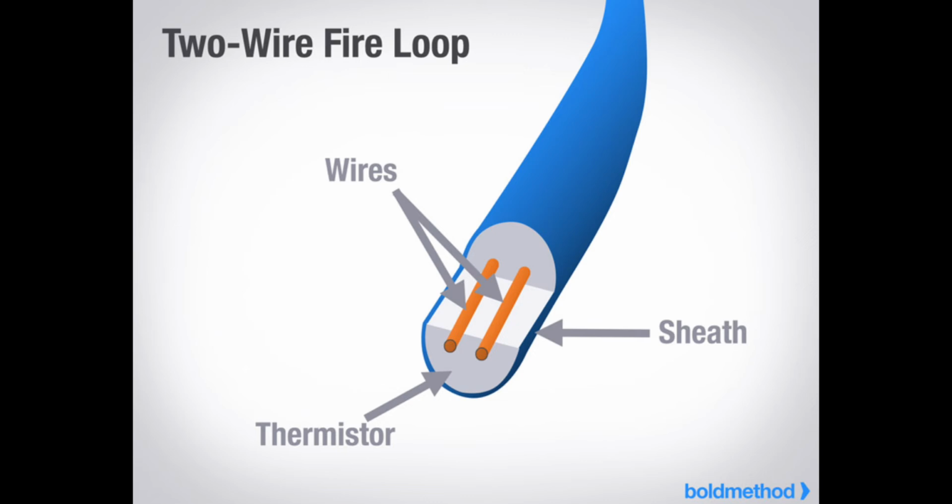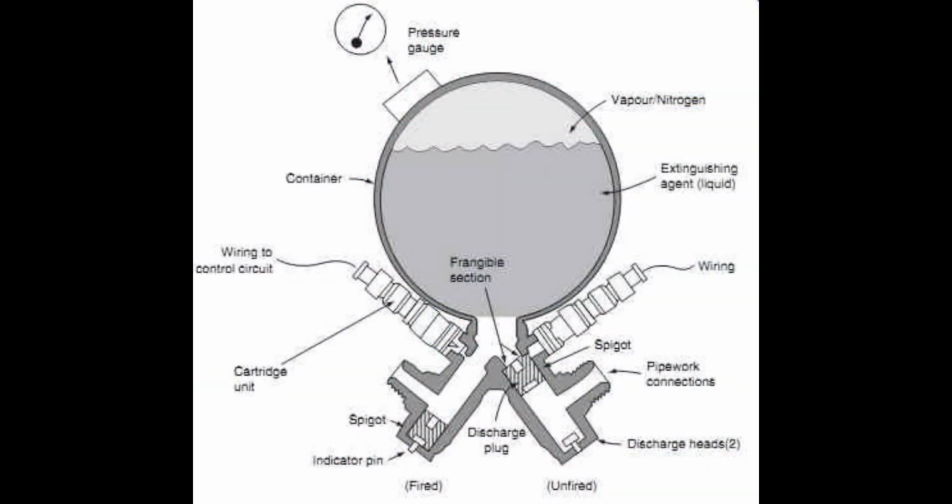What are two types of fire extinguishing systems? High rate of discharge system uses halon, and conventional fire systems use carbon dioxide. In a turbine engine Freon fire extinguishing system, how are bottles discharged? Electrically detonated explosive discharge cartridge, squib, breaking a frangible disc.